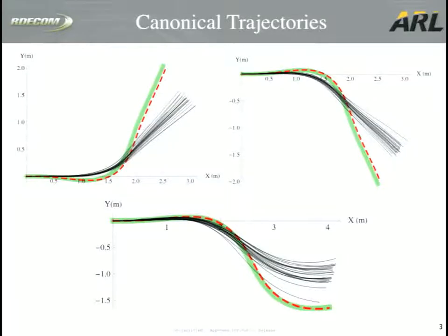Previous work has focused on how you can explain trajectories over entire missions, the odometry problem essentially. We're interested in the related problem of trying to take a time-varying control input and then be able to predict the motion over a relatively short time horizon. In particular, we study the statistics of those motions over repeated executions. To that end, we'll be considering 3 canonical trajectories, a left turn, a right turn, and an S-curve, and then looking at data captured with the motion capture system over many runs again to look at model uncertainty.